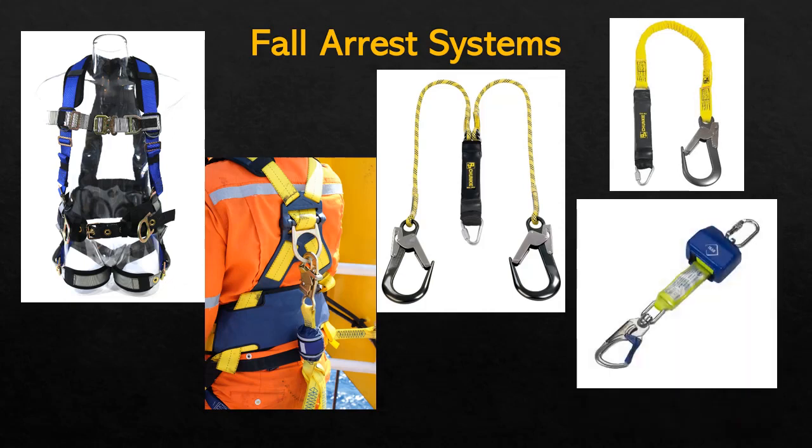The type of lanyard you see here is another type of shock-absorbing lanyard, but this one works more like a safety belt in a car, in that when you're walking, you can keep pulling out a little bit more of the reel, so you can get a longer lanyard. But then once it senses a sudden jerk, it locks up. So just like a safety belt in a car, these are designed so that if a person, say, trips and falls over, it automatically freezes up, so nobody gets exposed to more than just a person-height fall. So these are the types of systems you see.